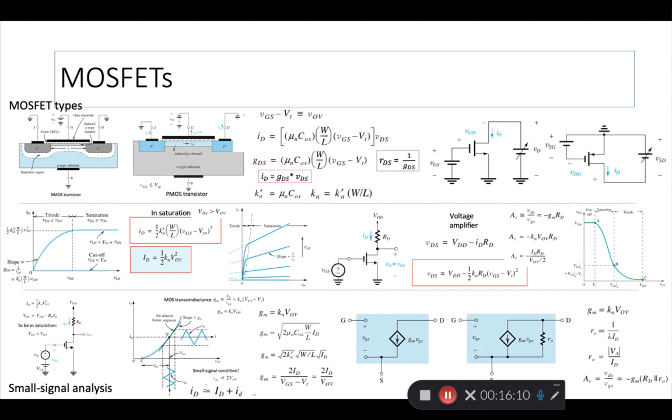So to be able to do that, just like we did for the BJT, you run this drain current through a resistor and you pick the output voltage off of that resistor. Then you can write this nice KVL that says V output equals some fixed value minus the independent variable ID times RD. You can modify that to show it in terms of input voltages. If you don't want to mess with the current, then VDS, the output voltage, equals constant minus something times input voltage, right? So the input and output voltages are related in this way.